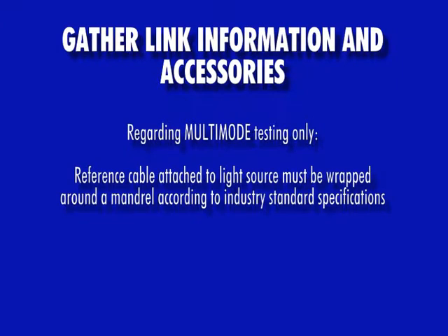Finally, if testing multimode fiber, the launch cable attached to the light source will also need to be wrapped around a mandrel according to cabling standards specifications. Refer to OWL's video on mandrels for more information.